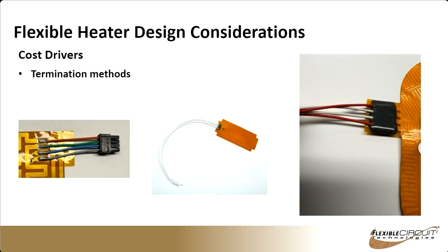Yeah, if you look at that image there, that dot of epoxy covering that component is probably less height than the lead wires. Yeah, and you'll notice that on all three of these here, you're seeing 4 wires coming off, and I would say that we have some type of temperature sensing that we put on virtually everything that we do. And the reason there's 4 wires is the 2 of those will be servicing your NTCs, and the other 2 are your power leads. So that's the most common way of doing it. And we do put a lot of components on our heaters.